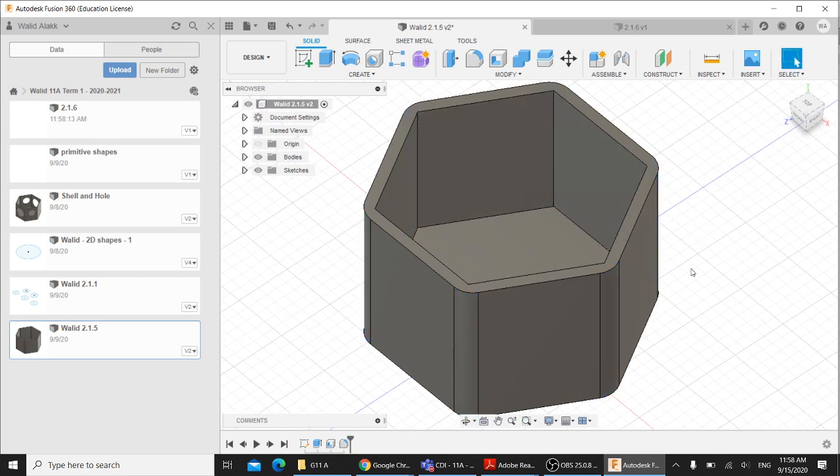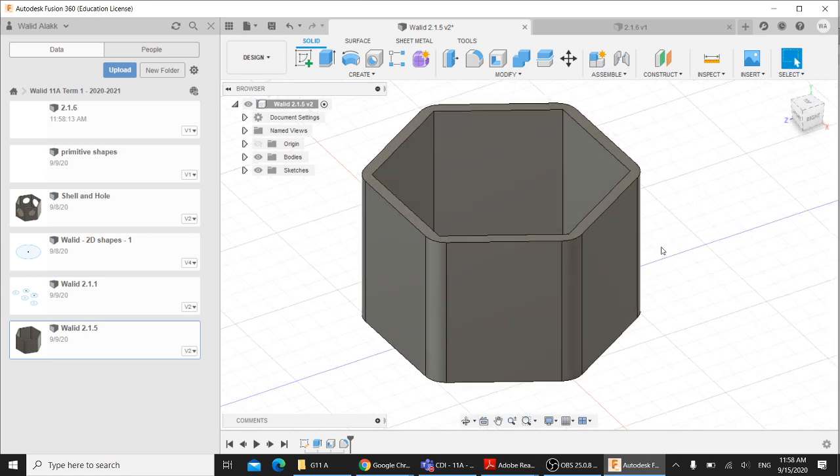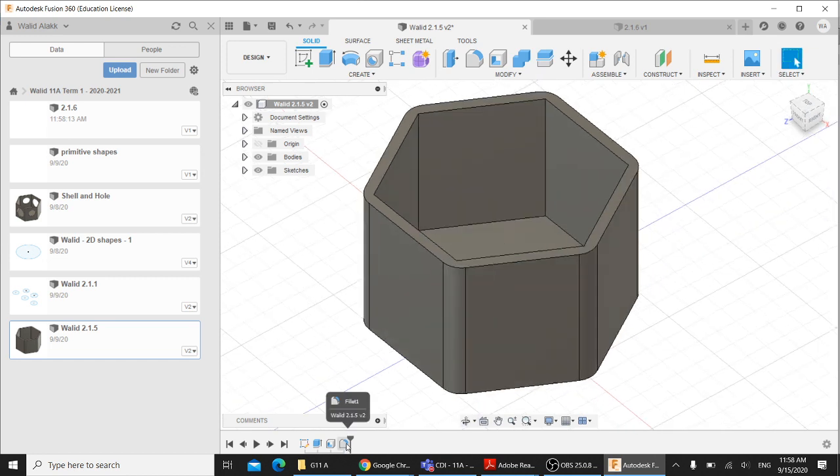How can I create a fillet for the inside edge? There are actually 2 ways. One easy way and one tricky way is to move the fillet to be before the extrude that we already made. In this case, we will make a fillet for the inside and the outside edge.